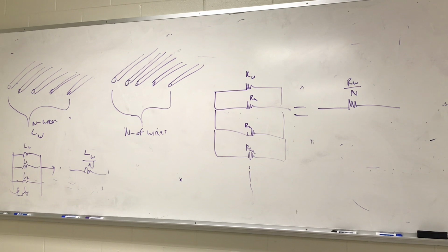And the chassis ground and the earth ground can be different for one reason, because there are actually wires connecting, and the current that flows through there will cause a voltage difference between the two. And there's something called a signal ground, like if you have a chassis, say a metal box that has a ground where things are measured against. But then you have chips themselves. Each one of those chips has something called a signal ground. And the signal ground and the chassis ground can be different. And there are methods to actually locate and connect grounds to prevent something called ground loops or unwanted effects. Basically, especially with lightning and stuff like this, they cause world-class problems.